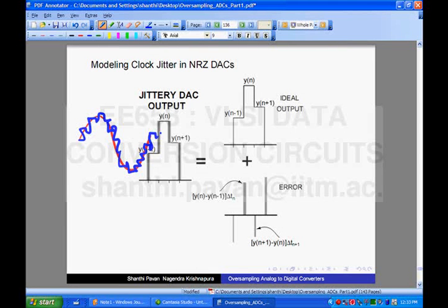Okay, no. What else? For a given quantizer and for a given order, when will the jumps around the nominal be much higher? There will be large jumps. No. Whether it's an RZ DAC or NRZ DAC, the output of the A to D converter will remain the same, right? The codes of the A to D converter will keep jumping up. What is the output of the A to D converter? Yeah, it is code, but what is it in the sigma delta loop? This is the A to D and this is the D to A, right?